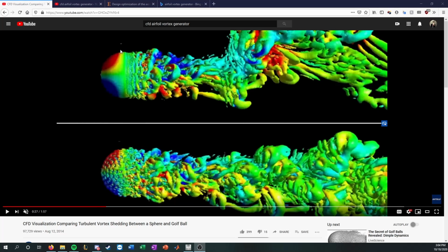to explain it, where you could have a simple golf ball with nothing, a simple perfect golf ball with no indentations, and it will fly in the air and create a vortex behind it because there's separation. But if you indent it and have these little divots or dimples, you create mini vortexes on the surface, and those vortexes travel down and help energize and actually streamline the golf ball. So in the case of a golf ball, I believe it helps reduce drag and it helps the wake stay centralized and together, so the golf balls basically fly farther. And this is why golf balls are constantly getting better and better, through the optimization of vortex generators.